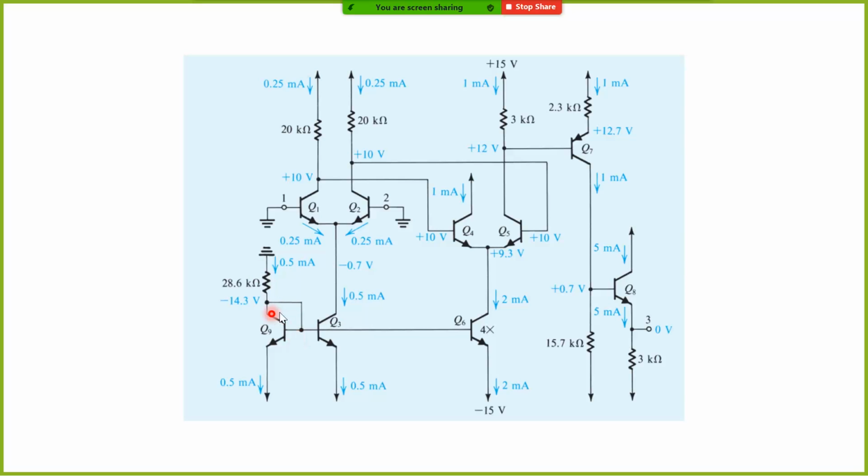current mirror. I mentioned about current mirror. So this is the current source. You have 20K, 20K. Two inputs are going to the next stage. So this is a multi-stage differential amplifier. In the second stage, Q4 and Q5 form the second stage. I took this from Sedra Smith. You'll find it in the textbook. You can go through the analysis of this one.